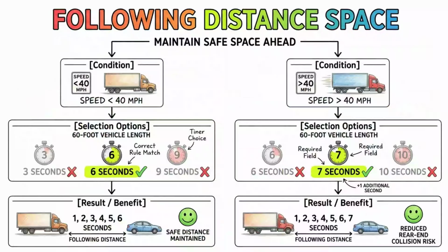Beyond the rubber of the tires, you must also carefully inspect the wheels and rims. You are looking for any bends, cracks, or welding repairs, because welding on a commercial wheel rim is strictly prohibited and extremely dangerous. Next, you will check all the lug nuts to ensure none are missing or loose. A classic sign of a loose lug nut that examiners want you to know is the presence of rust trails out from the nut, or shiny metal threads exposed on the bolt. If you see those rust trails during a real-world inspection, you know you have a loose wheel that needs immediate attention.